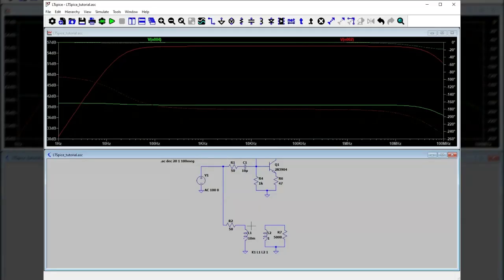So 1 volt here, 10 volts here. 1 milliamp here, 10 milliamps there. Constant power just changes the voltage current ratio. And when you go up by a factor of 10 in voltage and down by a factor of 10 in current, then voltage divided by current is 100 times higher on this side than on that side. So it all makes sense if you think about it a little bit.